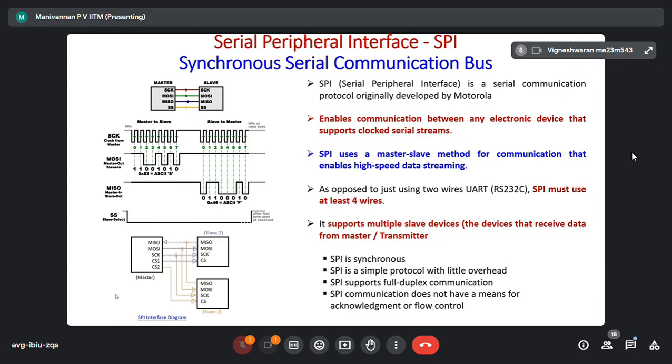In serial communication, data is transmitted as 1 byte with a start signal, stop signal, and parity signal, with 8 or 7-bit data. That is byte by byte. Then you will send. But in SPI, it need not be a byte. It can be 16-bit or 32-bit or 64. One piece of information itself can be a big number. It can be longer. That is what is possible. But accordingly, the number of clocks will also be there. Correct? So I say this is 32-bit. My data is something like this.